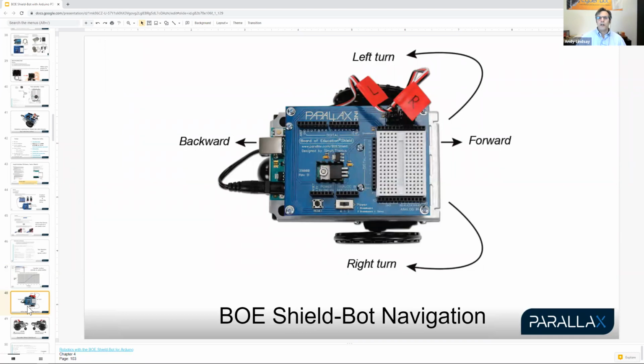Then you had some homework to put the robot together, since the servos had been centered and were ready to go in, with the suggestion to put them in the robot in the way that's a little more difficult to access for re-centering the servos, but is higher performance and runs nicer, with the axles closest to the center of the robot. So does everybody have something that looks like this?